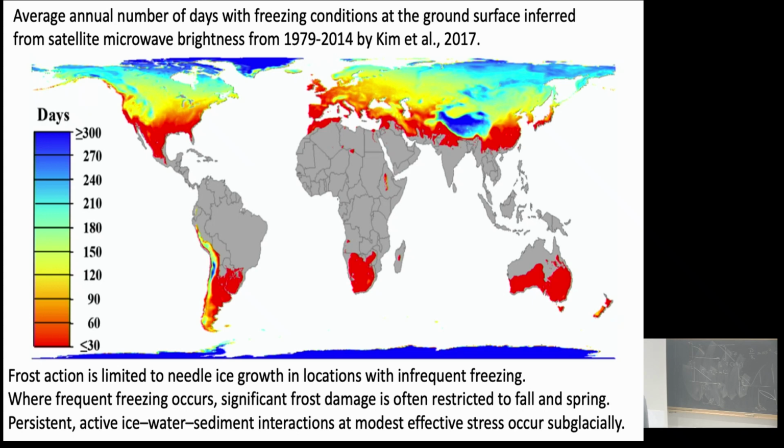In these more yellow regions and the light blues, we can start getting frost heave in those sorts of regions. Of course, it depends upon the distribution of time at different temperatures, and that's not reflected in this map. But these are the places where we get frost heave and where we have to worry about it getting very muddy in the springtime because of all that ice melting and having nowhere to go because the underlying substrate is still frozen, and so it's impermeable.